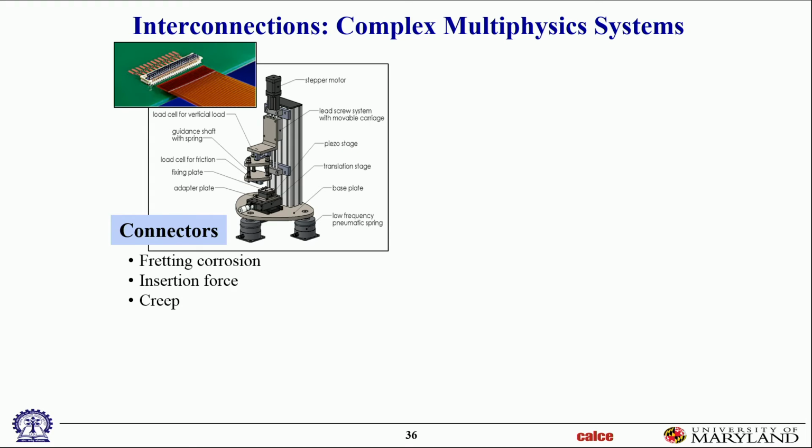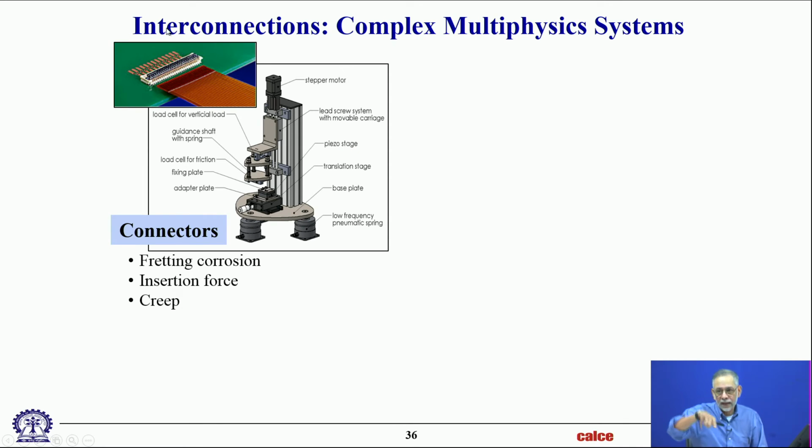The thermal expansion mismatches due to heating and cooling cause micromotion that will wear out the gold. So wear resistance is also a key issue. And the wear resistance is not just the metal, it's also the interface between the base metal and the surface metal. So we do a lot of tests on wearability, wear characteristics of the coatings. This is just a little tool that we use for that kind of fretting corrosion.